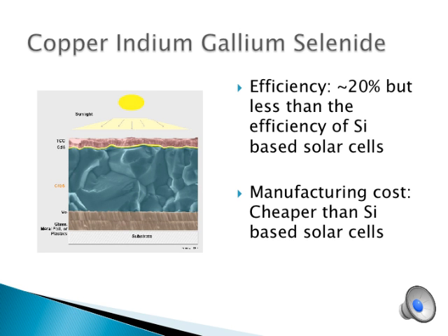Recently, cadmium telluride has emerged as a popular choice for producing high volume and low cost solar modules. Its bandgap is almost perfectly matched to the distribution of photons in the solar spectrum in terms of optimal conversion to electricity. The manufacturing cost of cadmium telluride is 76 cents per watt. The total capital cost is 90 cents per watt. The efficiency of cadmium telluride is about 11%.